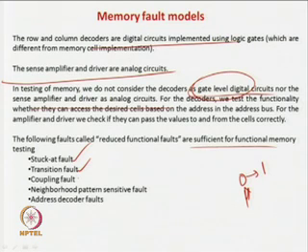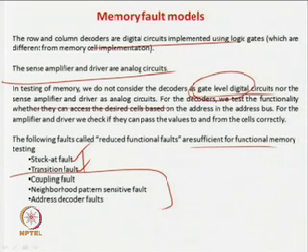Coupling fault, one very important. So, these are two standard faults, like you should be able to go from 0 to 1 and 1 to 0. These are also available in sequential and combinational circuits, although we have discussed only stuck-at models, but transition faults, delay faults, bridging faults are also considered in the case of sequential and combinational circuits. But these are some of the other very important tests which generally exist in memory, which is called the coupling fault.